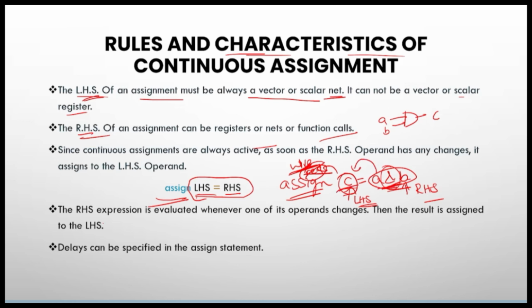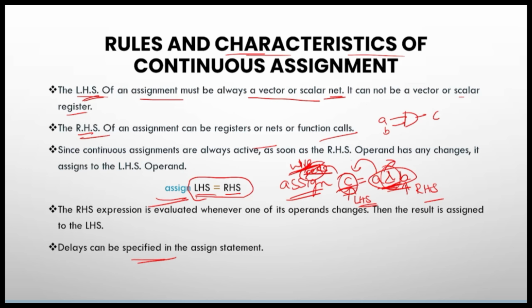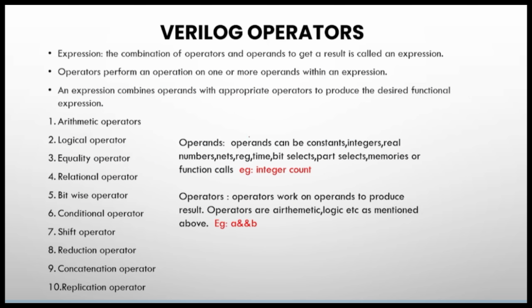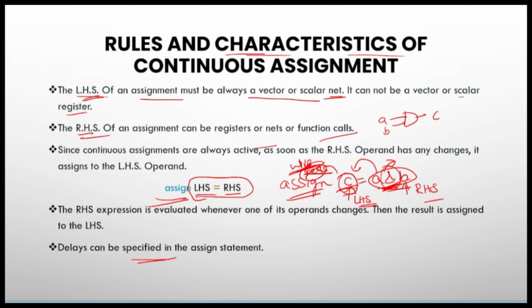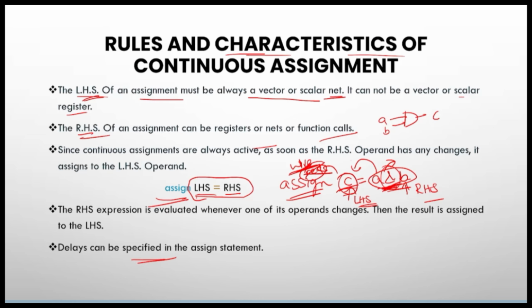If you are having any delays, you can also use the delays in data flow modeling. If you see here, this is my logic, using the operator. In this way you can use all these operators in order to build your logic in case of continuous assignment, which is the data flow modeling. In this data flow modeling, the continuous assignment is being done. That means the assignment is done continuously to this particular LHS and RHS values.